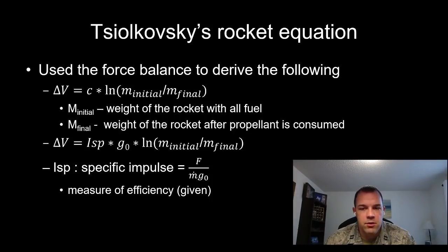And again, remember back to Newton's equation, if we're talking about momentum, either you throw more stuff out the back or you throw it out faster to get more thrust. And it's usually more efficient, it's always more efficient to throw it out faster. And so we'll see specific impulse, the higher the number, the better here. And we'll see for some of those electric thrusters where you're shooting out ions extremely fast, that the specific impulse will be outrageously large because we can accelerate those ions to relativistic speeds. Maybe not relativistic, but extremely fast speeds, tens of times faster than what you can get with chemical rockets.